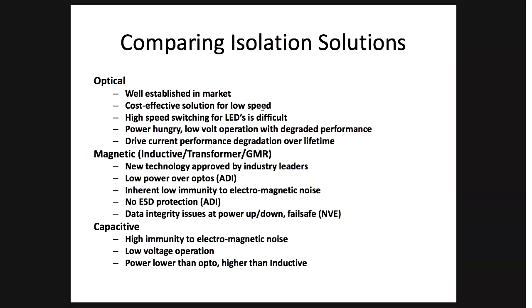Low speed means if you use it for data communication, suppose your data rate is very high; for DC it is fine. You want to isolate the analog DC part, digital DC part, or some different part of the DC part, the optocoupler is the best solution. But an optocoupler can also be used to isolate signals. Then what signals? If the frequency of the signal or data rate is very high, then it is not good. Only low speed can be used.